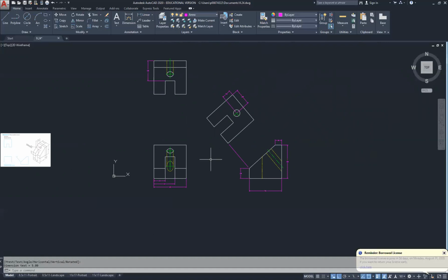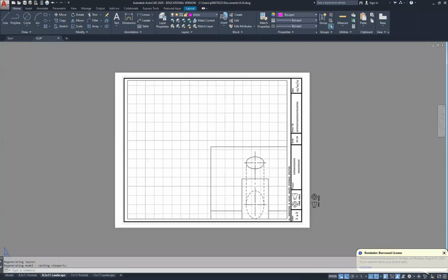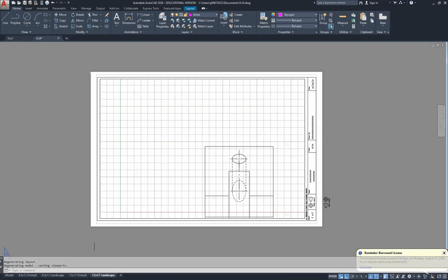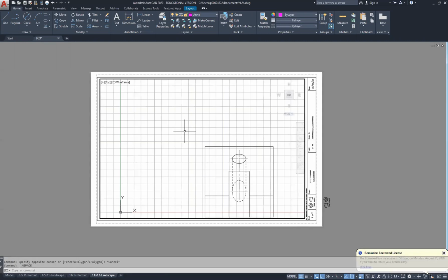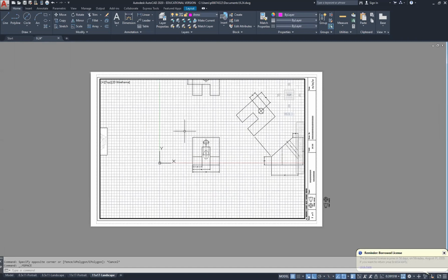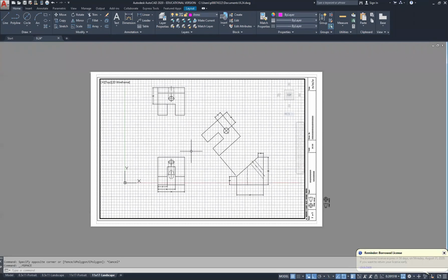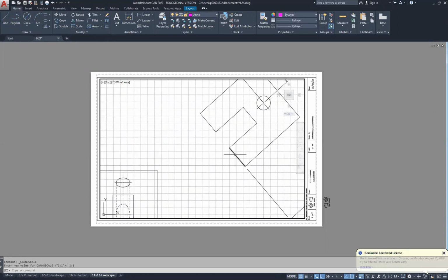Let's go ahead and check out our layout. Let's try an A-size sheet. I'm going to double click on the center area there. I drew all the dimensions at 1:1. Looking at that scale, you can obviously see that will not fit. Let's try an 11:17 inside that layout. Try it at 1:1. Too small. So I'm going to have to change this to 1:2.